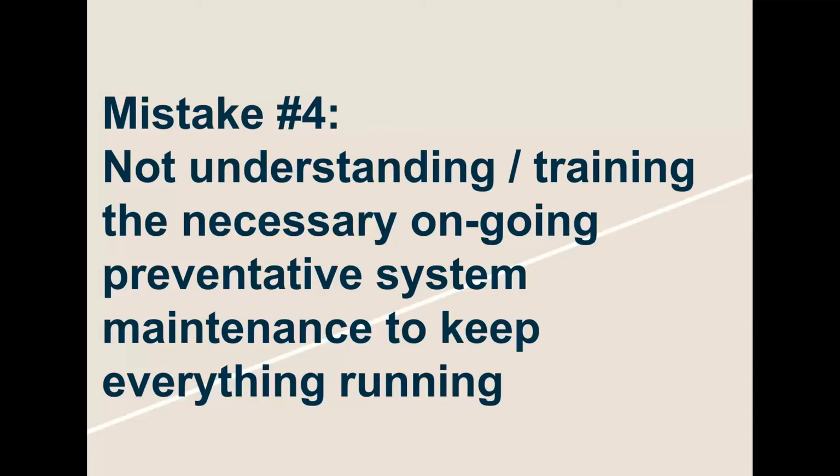And so as we dug deeper and deeper, we found that the other manufacturer's sensor that they had been using would just fall asleep. And there was no notice, there was no warning. Nothing happened at the sensor level to warn that this was going to happen. And because they'd had this happen a few times and corporate was so scared about it, they forced them to bump test once a week every single one of the units in the system. And so it really came down to, from a preventative maintenance standpoint, that was all that they knew to do. So that's kind of one end of the spectrum.